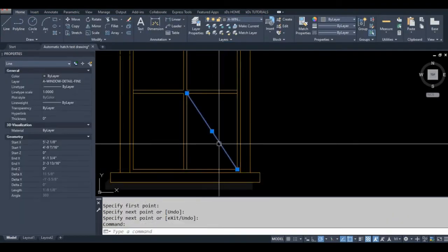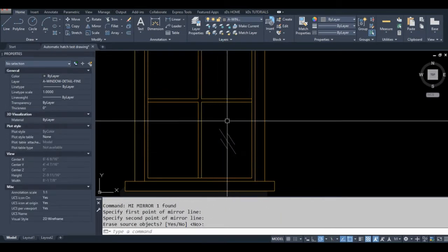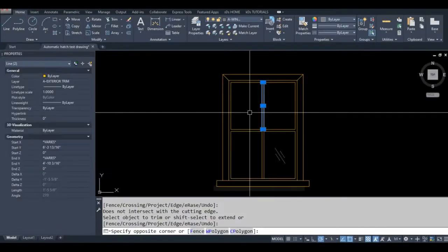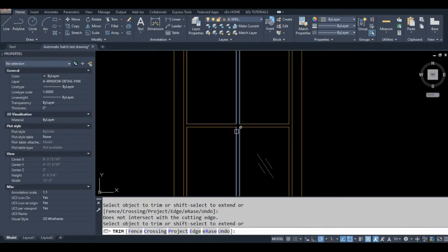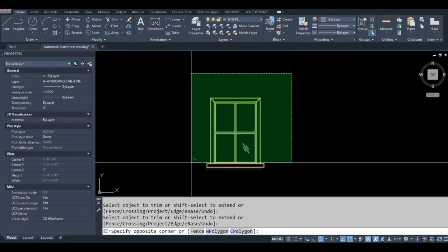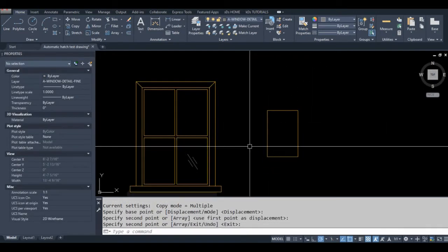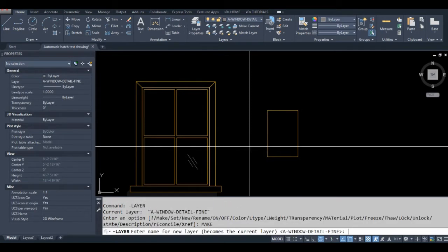Since I'm making yet another video on dynamic blocks and windows, I've decided to throw in a couple other neat tricks I've been using over the years. Making objects plot in true color, and adding simple shadow effects. The latter is really becoming outdated with all the 3D programs that can create dynamic shadows, but it's still useful if you want to make a quick and simple illustration without having to 3D model anything.